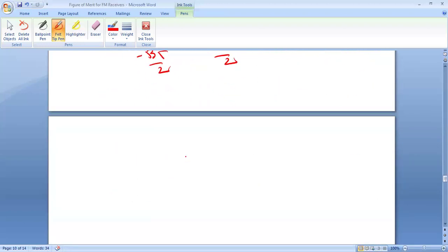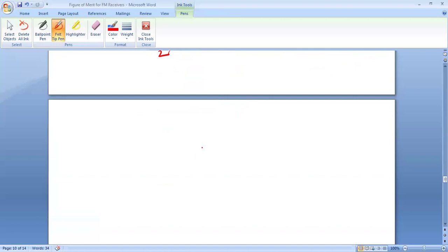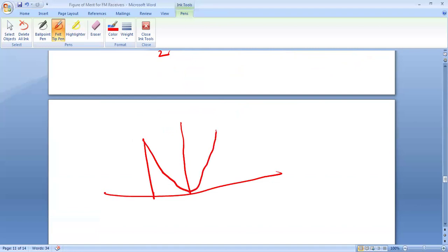Now, this is multiplied by f squared by A_C squared. So correspondingly, the power spectral density of the narrowband noise at the discriminator output is represented like this. That is equal to S_ND(f). This is frequency. Correspondingly, the term is N naught f squared by A_C squared.